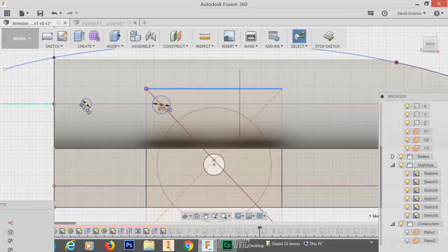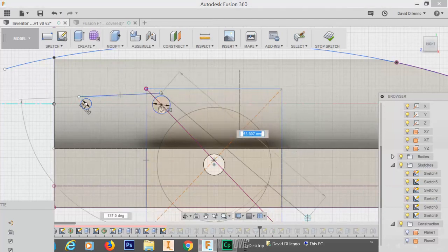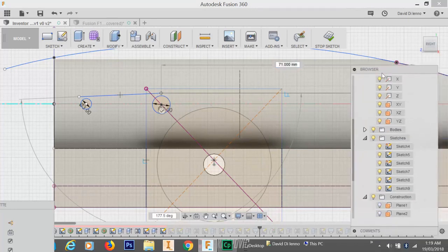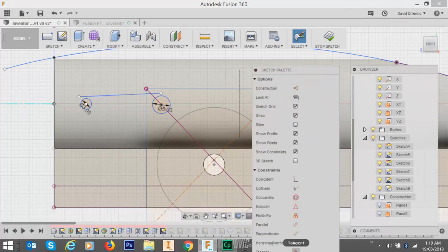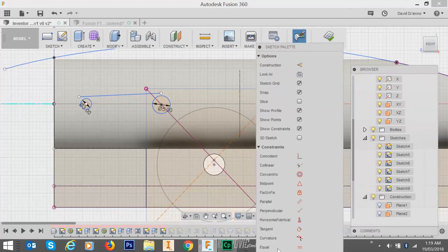Okay, next, create a sketch. I'll need a line, so they'll give me a line. And from here, I'll do a line across to there. Then I'll make use of the constraint features that I can find in the sketch palette. So let's look at tangency features down here. I want to constrain these lines and make this one a tangent to that. Select that, select this, and they are now tangent. Do the same thing here, select here, select there, and they are tangent.